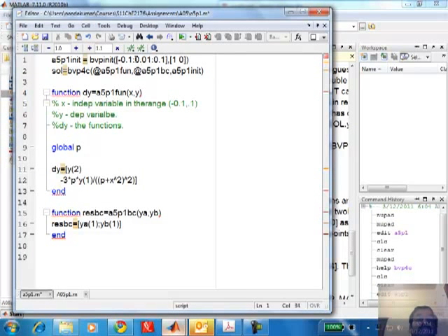So this is the left boundary, and this is the right boundary. I'm saying divide that into about 20 equal intervals in steps of 0.01. And this is the initial value over the entire range of x from minus 0.1 to 0.1. Assume y1 to be 1 and assume y2 to be 0. That's the initial guess that we are giving.